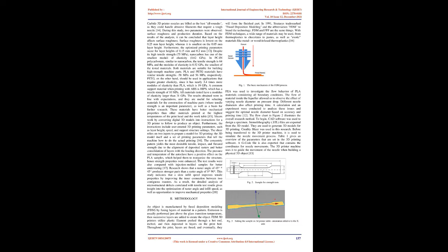Brass nozzles are easily machined, cheap, and widely available, which makes them ideal stock nozzles. Because it has excellent thermal conductivity, it is also used for exotic nozzles where the tip is made from a harder material. PLA, ABS, and PETG are the best options for soft plastic filaments. Metals and carbon fiber are non-particle additives that can be used in 3D printers. Steel is less thermally efficient than brass as a 3D printer nozzle. In particular, this can lead to inconsistent flow performance.